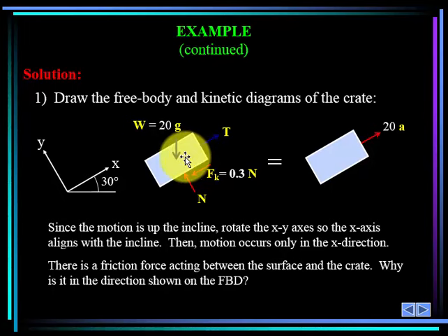Almost always, we're going to use a simple model of friction that says the friction force is equal to the appropriate coefficient of friction times the normal force, and here's the normal force. And the appropriate coefficient of friction for this problem, again, was given as the kinetic coefficient of friction, 0.3. We also put the rope tension on here, and several of these things are unknown,